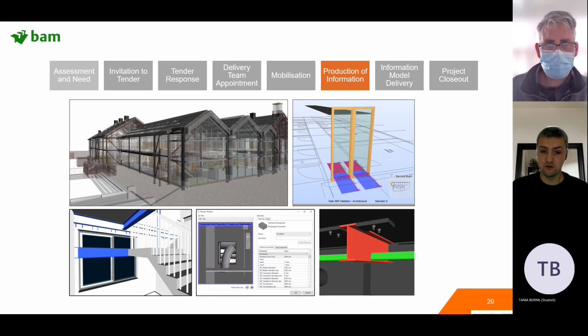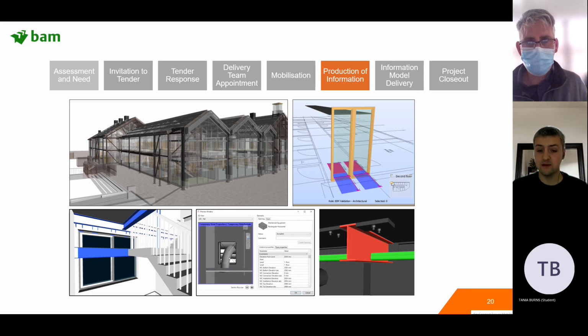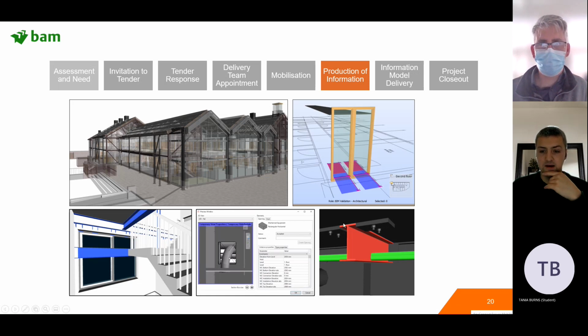It's a major cost for contractors on site to have to make these holes after the concrete has already been cast. It's really, really costly. So there's a major saving to using the right software to coordinate the M&E with the holes at that stage.